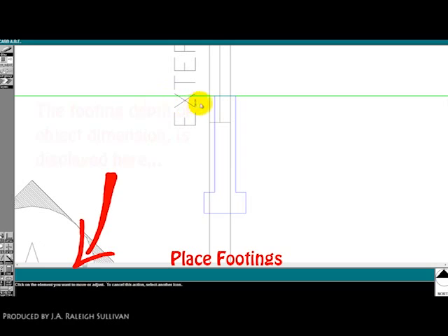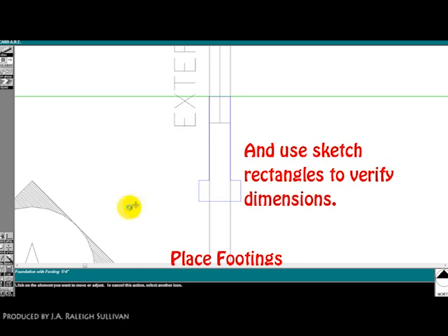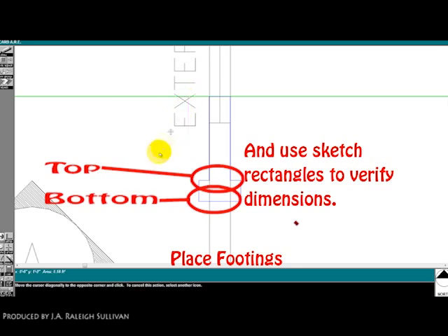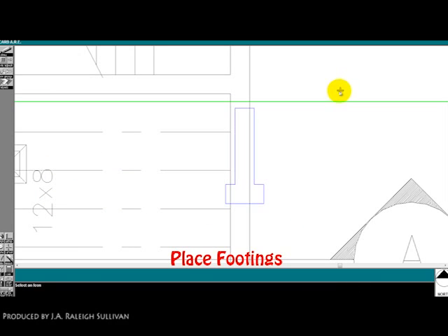There are 2 ways to do this. One is to have the top of the footing's base be at the frost depth, and the other is to have the bottom of the footing's base be at the frost depth. Either way is okay as long as the frost depth requirement is met. If you go longer than the frost depth, it could be considered wasteful of materials, and if you go shorter, then you won't be meeting the program requirements.